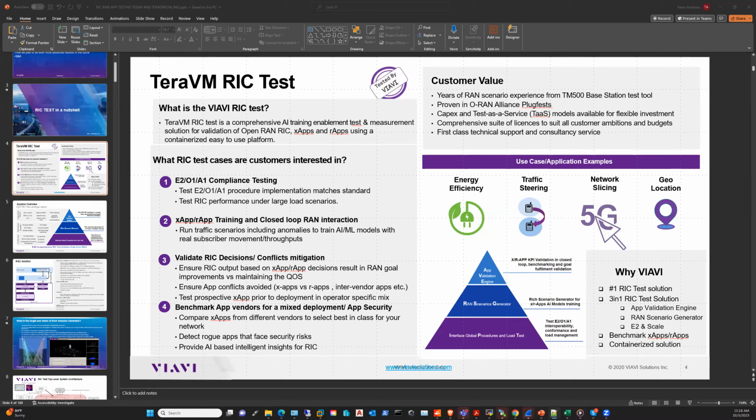As far as the antenna, you can set antenna tilt, azimuth, power, gain, and pattern, basically realistic commercial antenna patterns. In the RF environment, when you're defining your antenna, you can set UMa, UMi, rural, indoor, outdoor, and this is based on the 3GPP 38.901 spec.